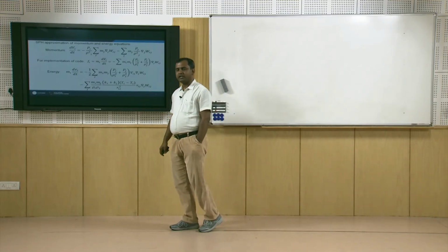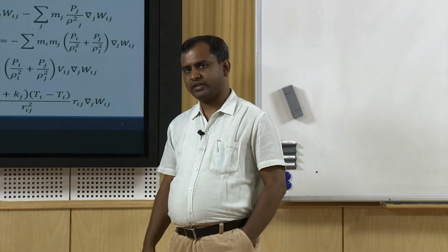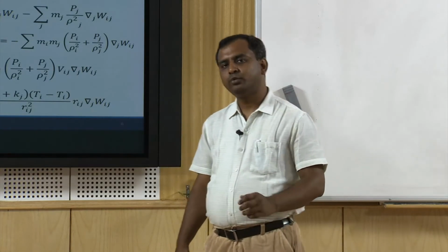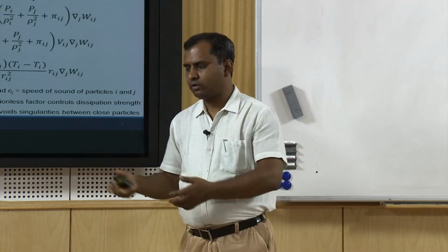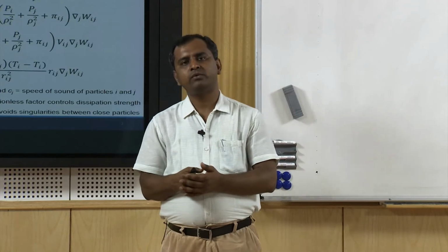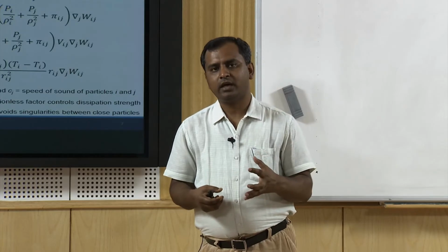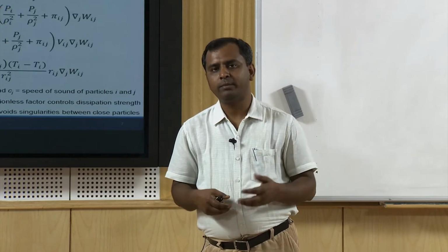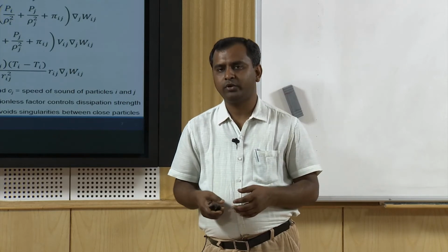One important thing we need to look at here is that nowhere is there a derivative of the field variable. So, the derivative is only over the smoothing function. Okay. Now, we know that in this methodology the domain has been discretized into particles. So, those particles will be breaking the continuum nature of the fluid. So, to gain back the continuum nature of the fluid, what do we need to do?